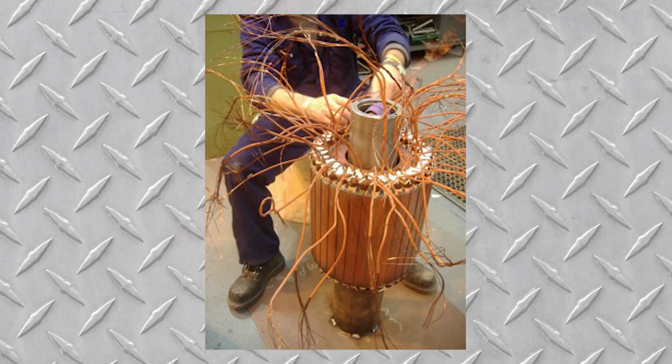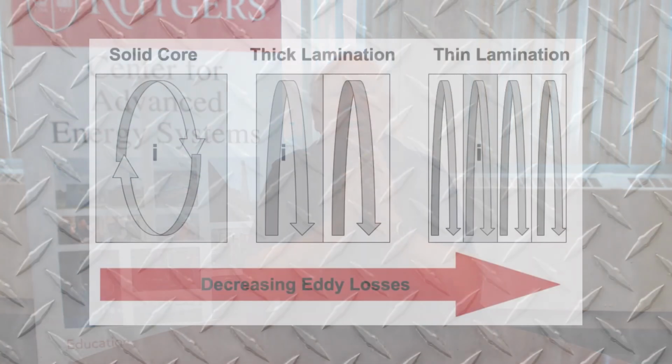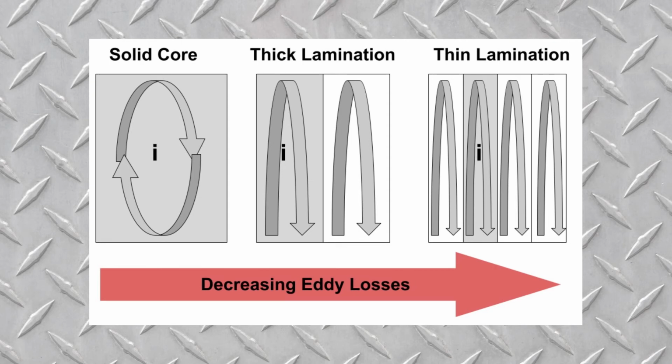Now, to appreciate one of the consequential problems, we have to talk a little bit about eddy currents. I know I'm not talking to a lot of electrical engineers here, but these windings that we make tend to go around a core, and typically this core is solid. If this core is solid and you're creating an electric field, you're going to find a lot of internal electric fields going around the solid core. So we're not going to use a perfectly solid core. And what you're going to do is make up your core with a bunch of thin laminations to try and keep these eddy currents from forming. Now, these laminations are thin and insulated from each other, and therefore they knock off these large eddy currents, which otherwise would reduce the efficiency of the motor.